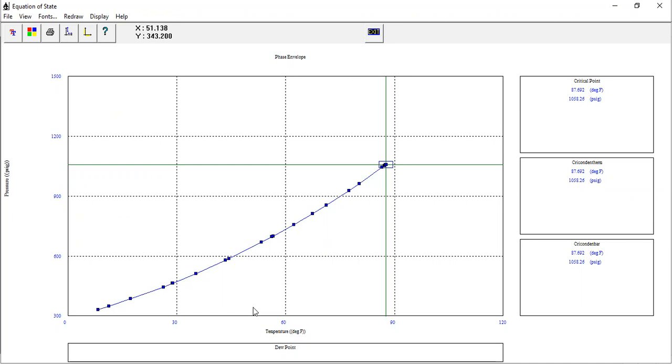50 somewhere here, and then go up, 582 at 50 degrees. You can see XY here. X is temperature. I just want to find 50, yeah, here, and then 582. Oh, this one is in gas phase. So at best case, I cannot achieve liquid CO2 at the bottom. I will lower down.